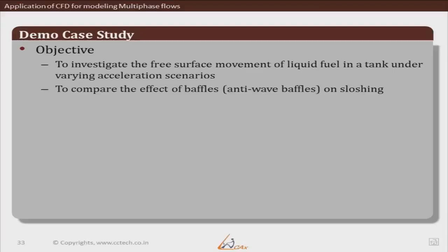The objective of this demo case was to investigate free surface movement of liquid fuel in the tank under varying acceleration scenarios. We also compared the effect of baffles on sloshing. Now what happens as physics is, wherever we have tanks containing a bulk volume of liquid, and there is a change in acceleration of that particular vehicle or tank, there is sloshing happening in that liquid.